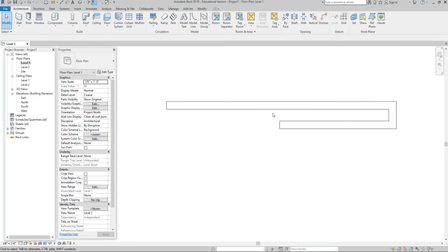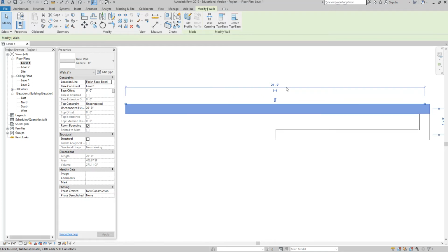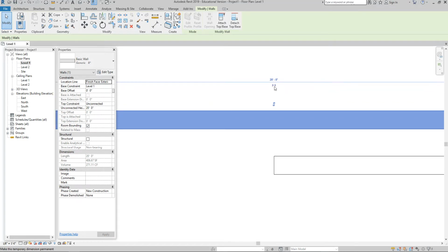So temporary dimensions allow you a visual connection when you're drawing. They allow you to alter the geometry after you've drawn it. And the third thing these temporary dimensions can do is become real dimensions. So if I click on my object, my temporary dimension pops up. There's this little symbol below the text, and it says, make this temporary dimension permanent. And if I click on that,